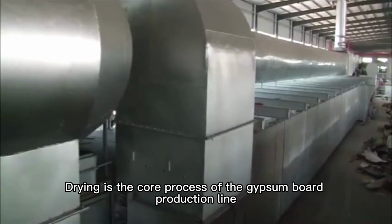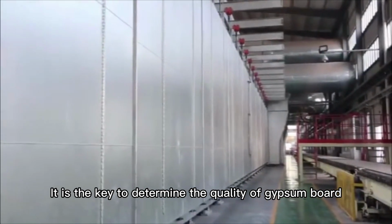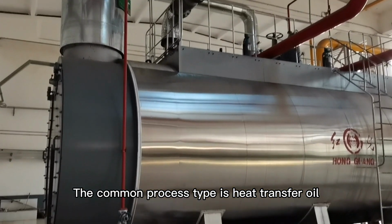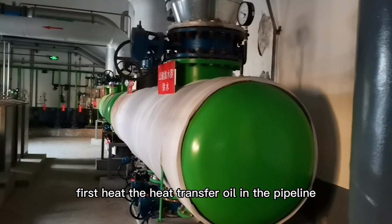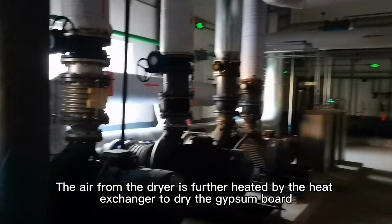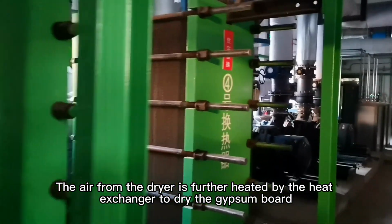Drying is the core process of the gypsum board production line. It is the key to determine the quality of gypsum board. The common process type is heat transfer oil. First, heat the heat transfer oil in the pipeline. The air from the dryer is further heated by the heat exchanger to dry the gypsum board.